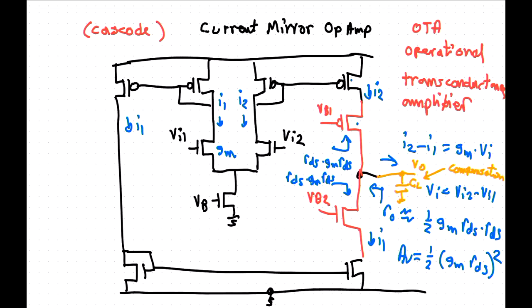So, yeah, that makes this a very nice amplifier. And you say the gain is only at the output. So what about the GM on your input pair, or if we put cascodes throughout? None of those things provide that. These are low impedance nodes. The impedance level in all of these nodes here is a diode-connected transistor. So look into the impedance there. That's about 1 on GM. On this node, and that node, and this node. And if we cascode it, it's even less.